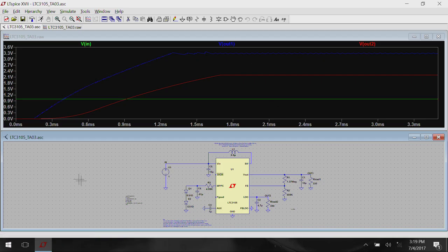In fact, you can do many interesting things before you conclude on these actual results. For instance, you change this input, because it can even start at 250 millivolt, put it to a lower voltage, and see what happens to V out. V out actually comes to stability much later. In some of my experiments which I propose to show you later, the 3.3 that you get here actually comes much later.